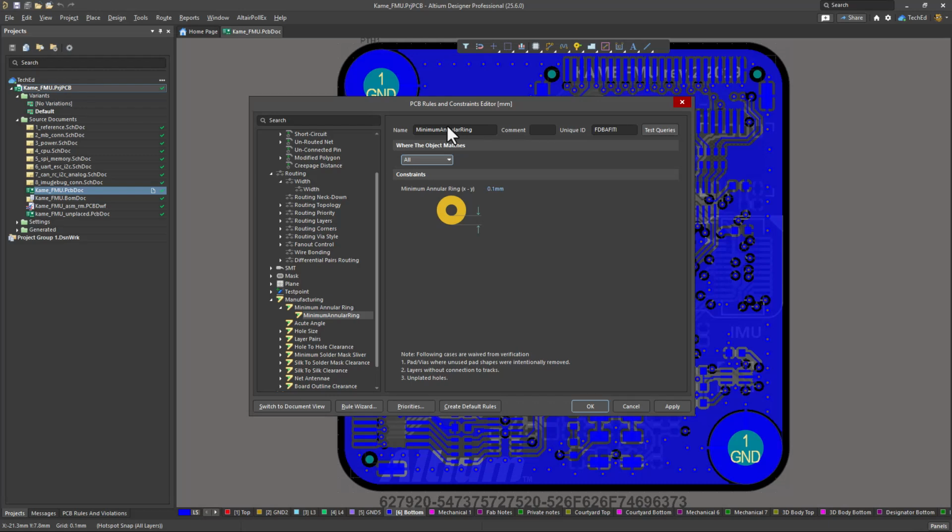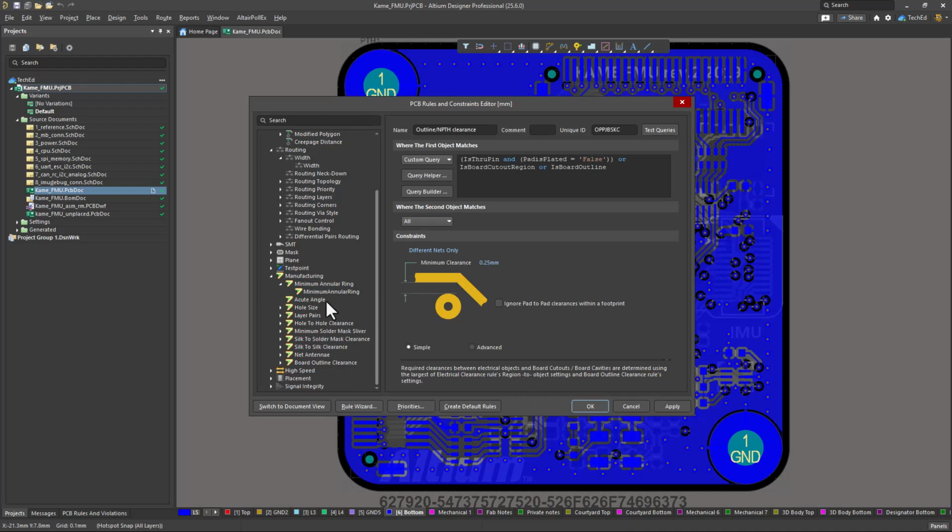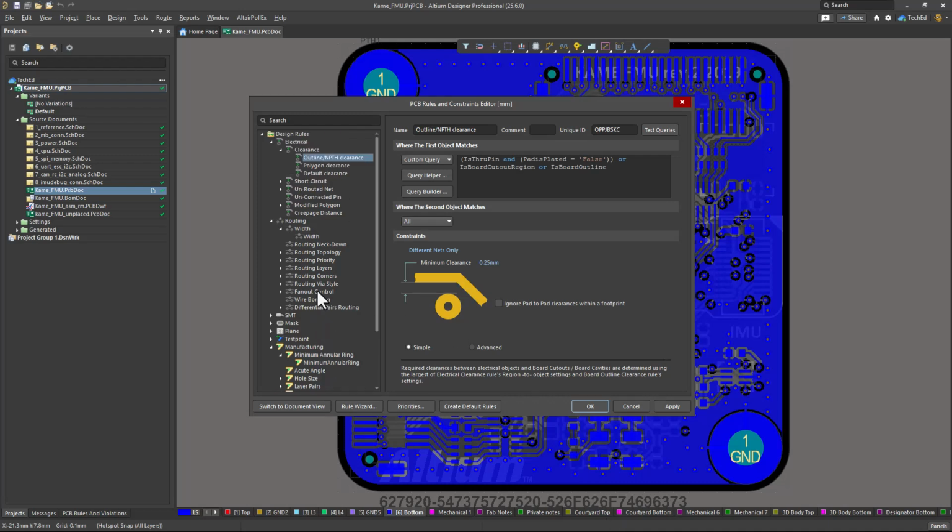Recently, I got a question about the constraint management and manufacturing errors you might get in a DFM tool if you're doing PCB design. In this video, I'll show you exactly where to set a setting for your DFM constraints, why they're different from the rules and constraints you would set in your standard design rules or electrical rules in Altium Designer. Okay, you'll understand what is annular ring and what resources you can use to get more informed about design for manufacturing.